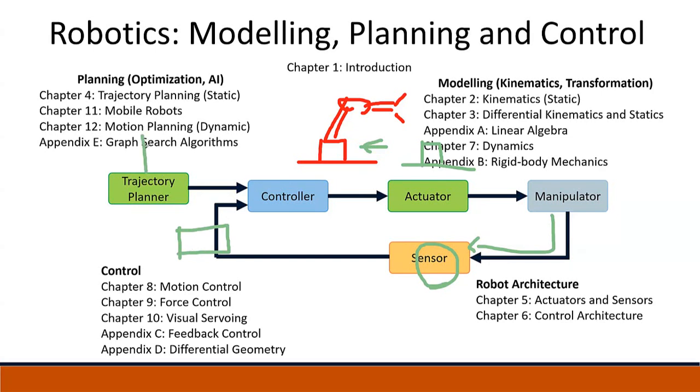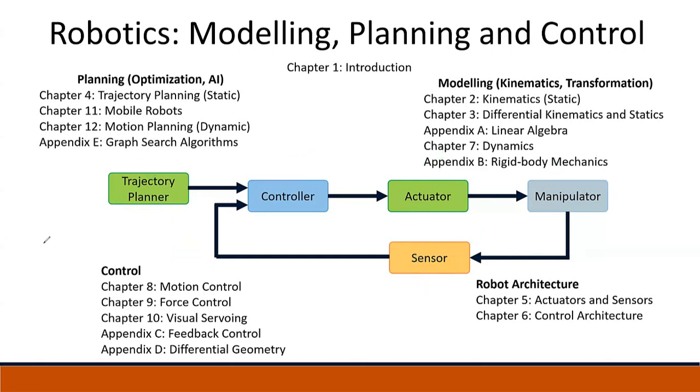And then you have your trajectory planner. You plan your robot arm, and based on the model you have, your controller does optimization control calculation and enables your actuator, and your actuator moves the motor of your robot arm, and then you try to reach for the object you want to reach. So this is actually a full feedback loop.